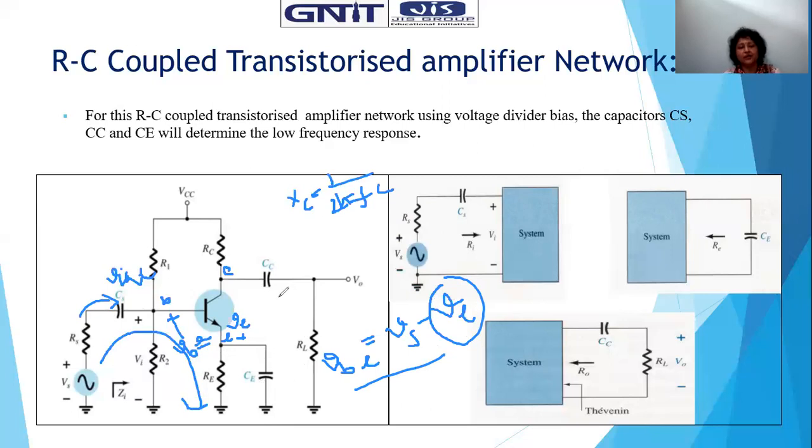Now my observation is that while all are series connected capacitors, we have to analyze with respect to AC. Today we will analyze for the low frequency range. So what is X? X is very high. If X is very high, the transistor may be equated as a resistive network, so it is an RC series network.